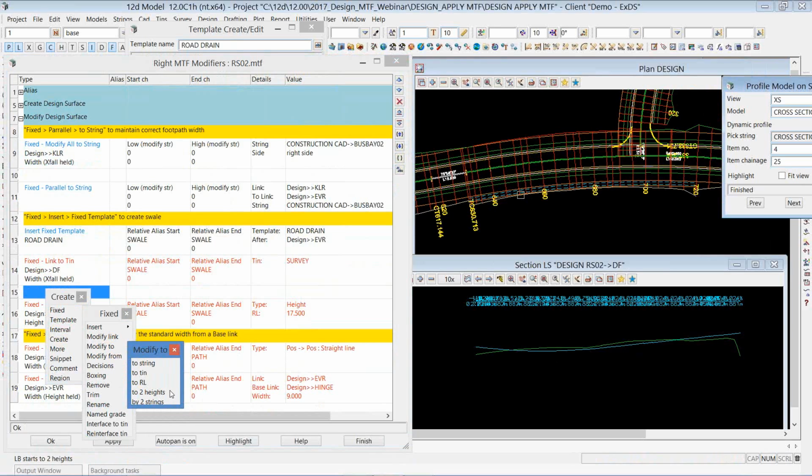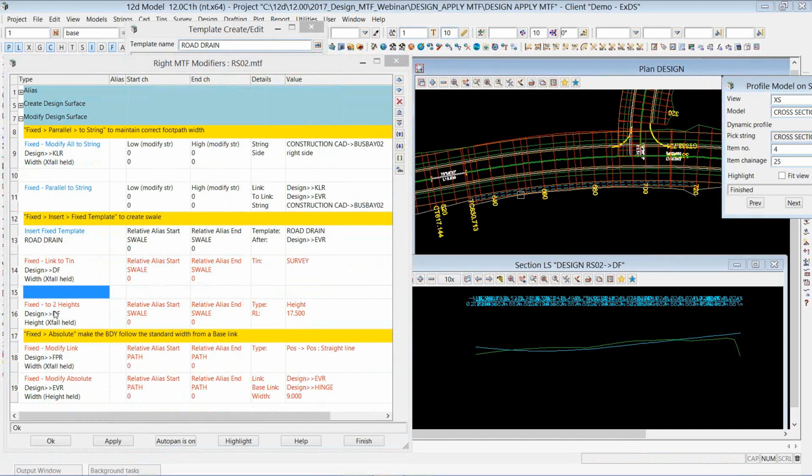So you want to not follow the center line grading for whatever case, and drain these like swales or benches out, especially if you're doing big earthworks. For highway designs, again, this is the one you might want to use to grade these strings independent of the center lines.